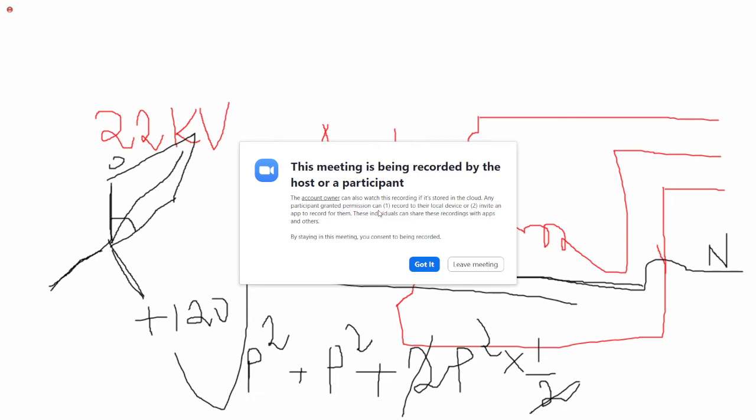Yes, sir. So you have understood three words by now. Line voltage, which is 440 for India, also merchant ships 440. You understood the phase voltage, which is 220, between phase and neutral. Got it? And then you have understood every country puts their neutral into the ground. Then next step we will understand why it is done so. Why neutral is put into the ground.